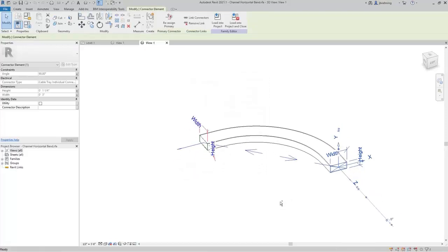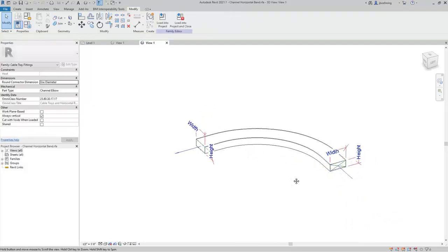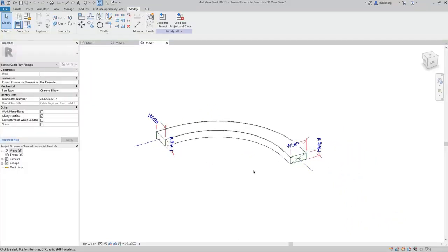If you notice these dashed lines in the drawing area, they simply indicate that the connectors have been linked. So you can see here there's a remove link option in the contextual ribbon, as well as a link connectors option, and when you see this dashed line it means that they've been linked together. So electrical connectors, those are going to control the circuits that they can be added to, and then cable tray and conduit, that's going to control your cable tray and conduit connections in the project, and the important thing there is really the size.